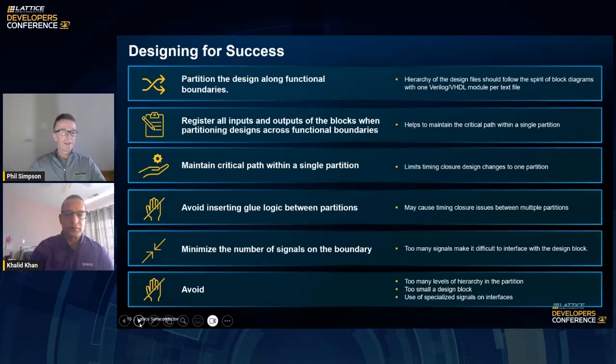In some applications, such as the secure, it may be that the application demands that you have a small partition or block, but generally having a bigger partition and having fewer partitions in the design will achieve better utilization and can help with the timing closure.